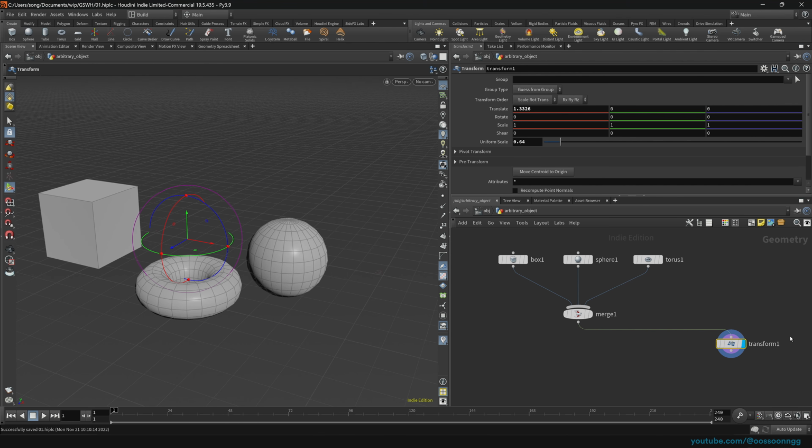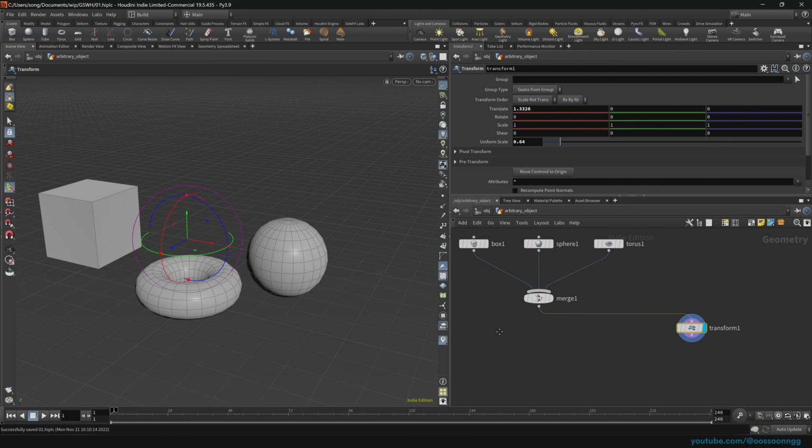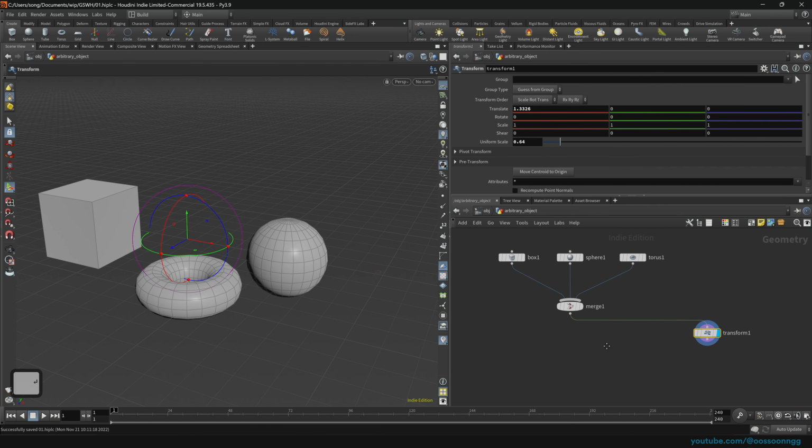When we're talking about the node trees, we don't need to hold down space bar. So just middle mouse button drag will tumble around, right mouse button will zoom in, zoom out. Again, it's faster than even scrolling. I prefer it that way. So that's probably the fastest way to move around.